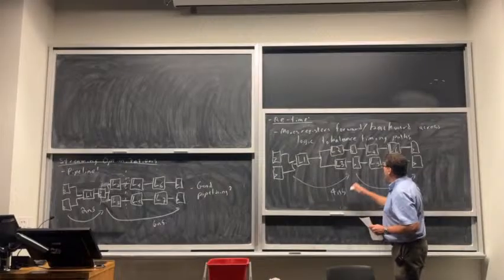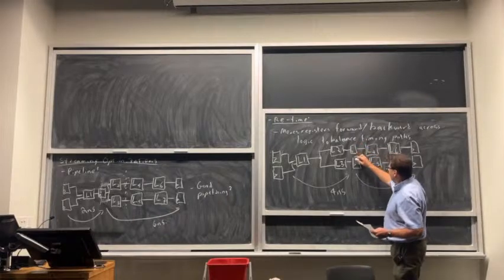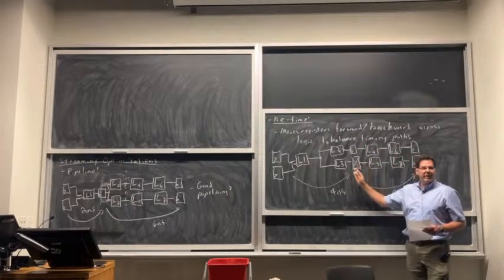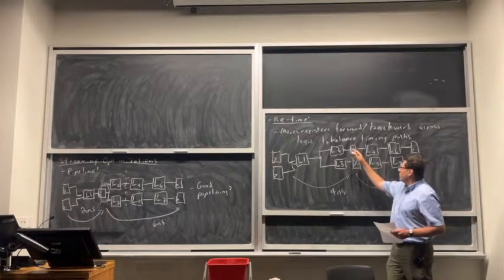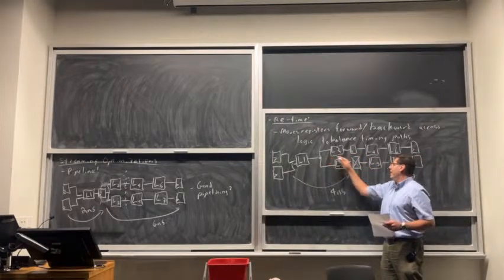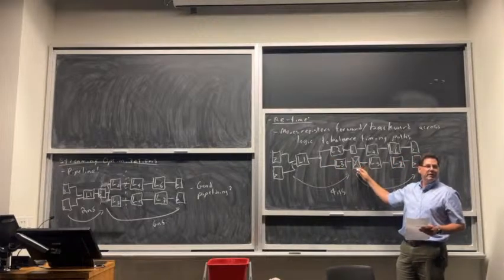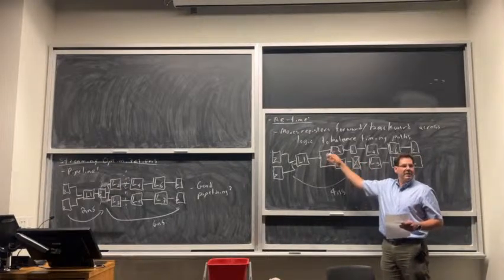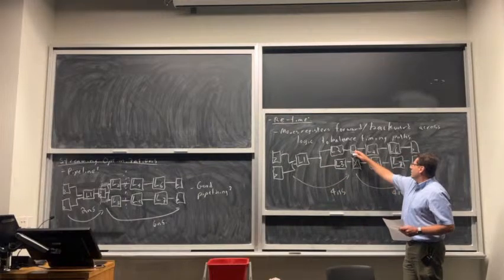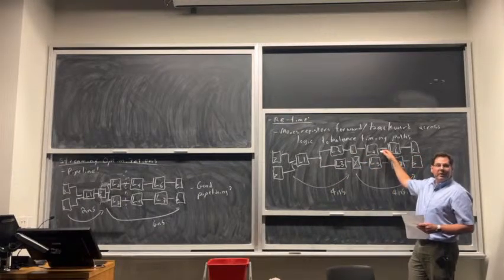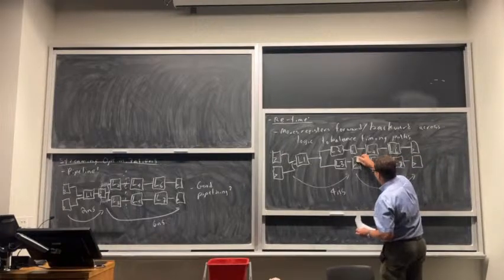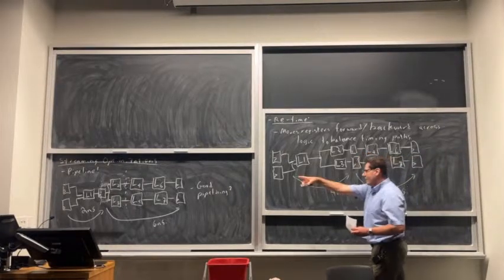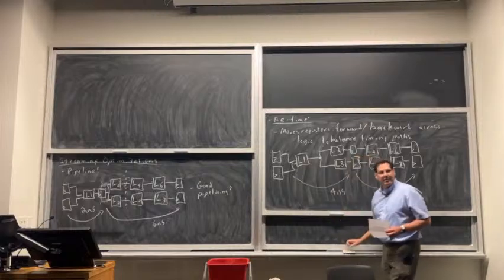If I actually change the circuit to have that register there, and I didn't have a register here, and that was my input, this is what I created, a retimer cannot move this register back to here because it doesn't match. There's no other register here that it can merge with and keep all the latencies the same. It could take it and move it there. That'd be okay. But the only way I would get in this state is if that was my input, right? So if that's my input, then I can get here, but I could never get to that other state.